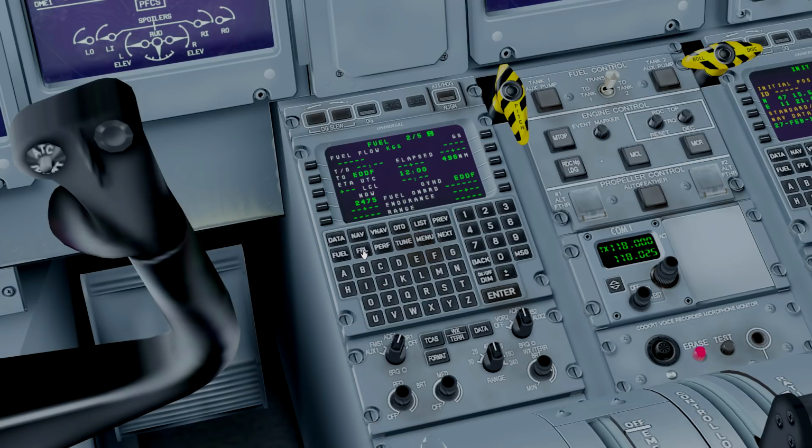What you can still do is go to the flight plan, and once in the flight plan menu, you can hit menu and then next page, and you can see here flight plan winds. So basically this allows you to enter winds at different waypoints. Now, it's a bit bothersome sometimes to enter wind at every single waypoint. So what you can also do is just enter the wind at some main waypoints that you're going to be flying over.